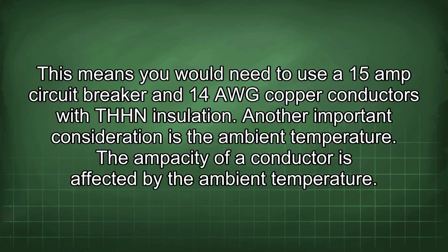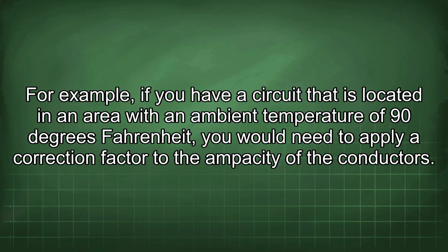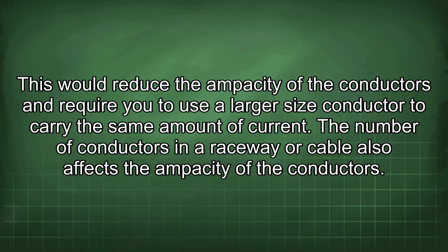Another important consideration is the ambient temperature. The ampacity of a conductor is affected by the ambient temperature. The higher the ambient temperature, the lower the ampacity of the conductor. The NEC provides correction factors for adjusting the ampacity of conductors based on the ambient temperature. For example, if you have a circuit that is located in an area with an ambient temperature of 90 degrees Fahrenheit, you would need to apply a correction factor to the ampacity of the conductors. This would reduce the ampacity of the conductors and require you to use a larger size conductor to carry the